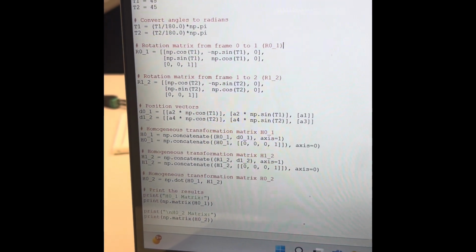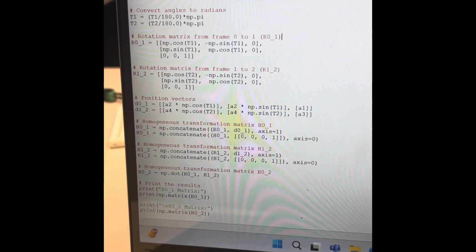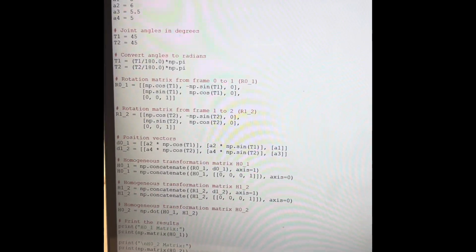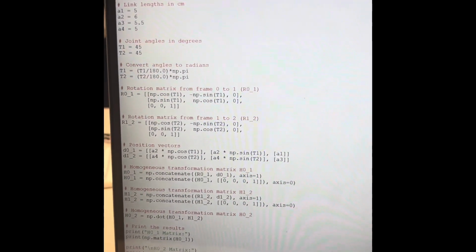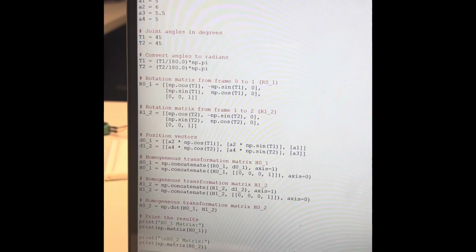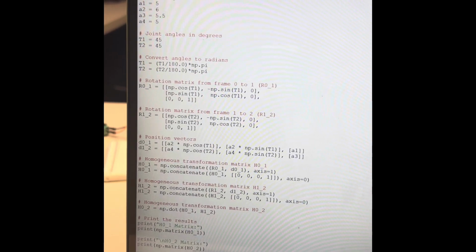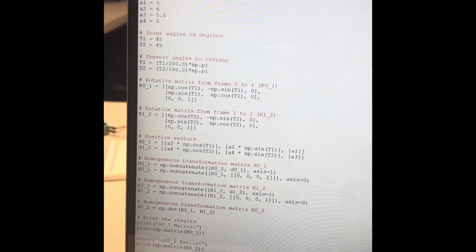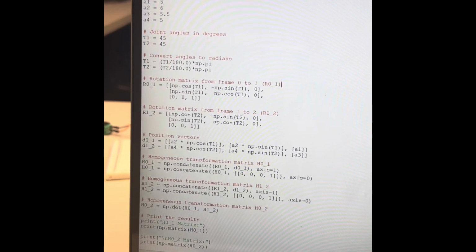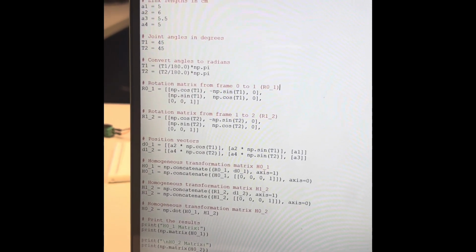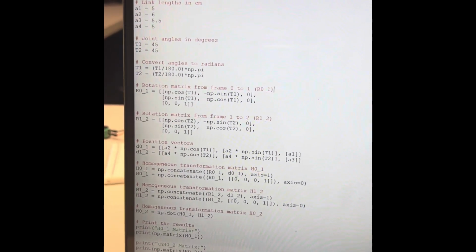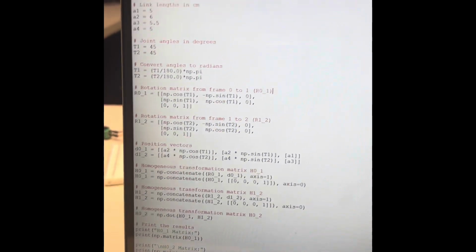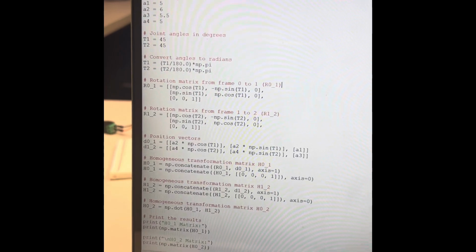Each line represents an important aspect that is used. We'll go one by one through the 14 lines to demonstrate and fully explain. Of course, for 1, import numpy, which will help with the linearity of the matrix. 2, define the lengths of the arms using the rulers that were given to us in the box, our mechatronics kit. 3, define joint angles in degrees.